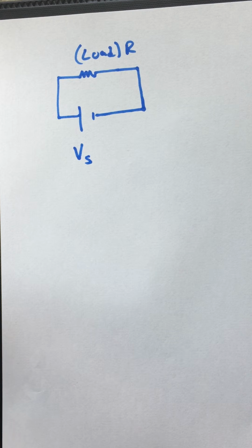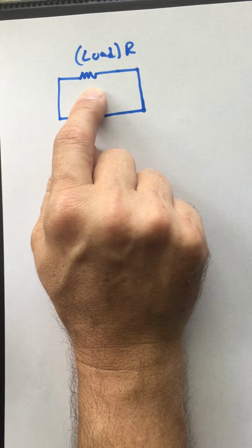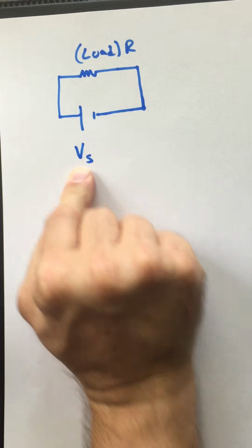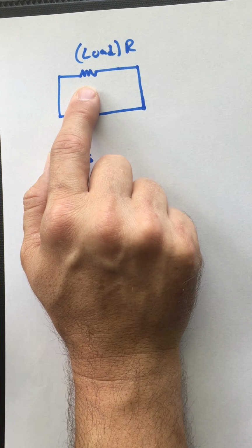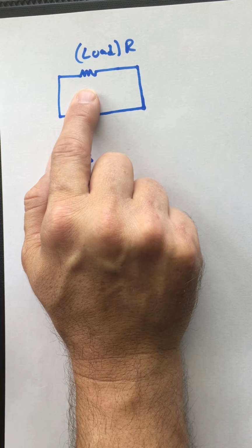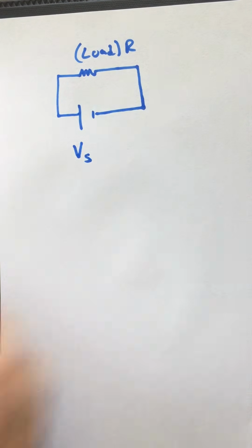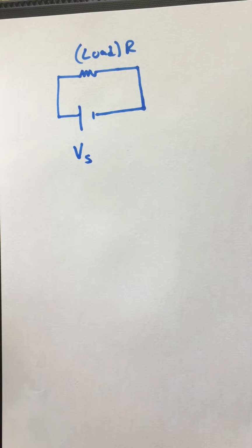Now, furthermore, let's assume that this load has some sort of electric motor. That's not hard to imagine, because a lot of things that we normally hook up to source voltages do, like hair dryers or blenders or air conditioning units or actual electric motors. Something in this load here is a motor. It's a coil of wire rotating in a magnetic field. All right, well, what is going to happen there? I'm going to induce an EMF in the coil, an EMF that opposes the motion.